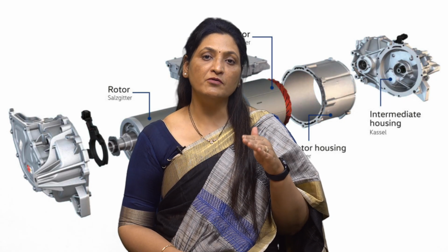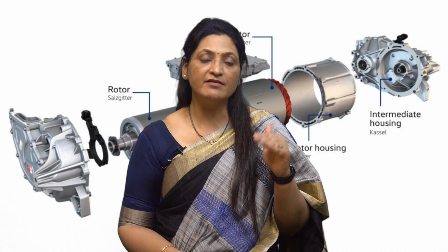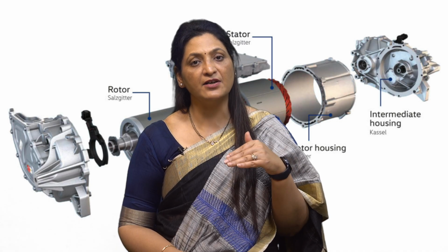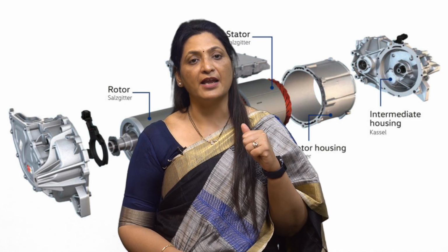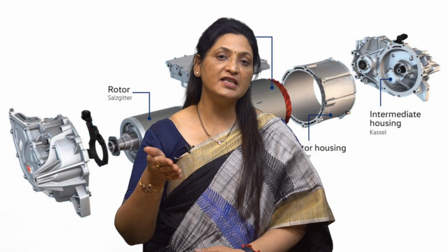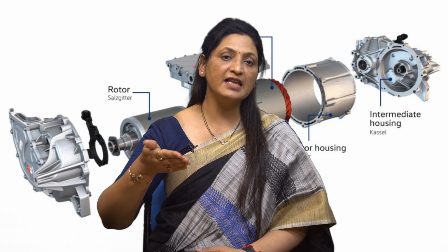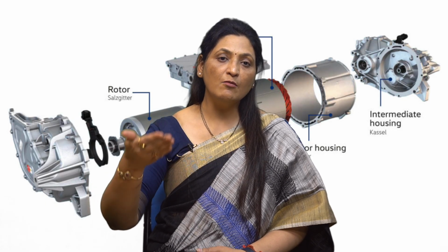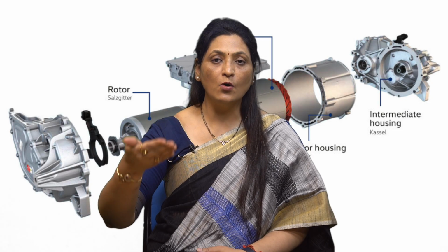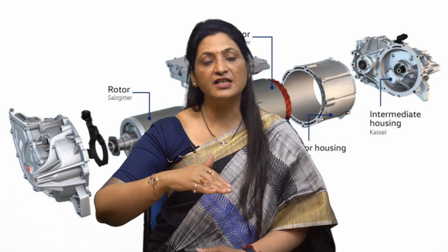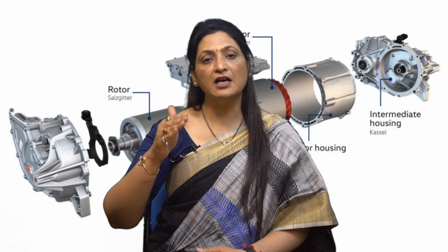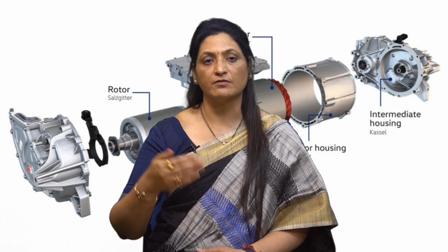During the light load period, the flywheel accelerates and stores the excess energy drawn from the supply, and during the peak load periods, the flywheel decelerates and supplies some of its stored energy to the load in addition to the energy supplied from the supply. Thus, the load demand is reduced.